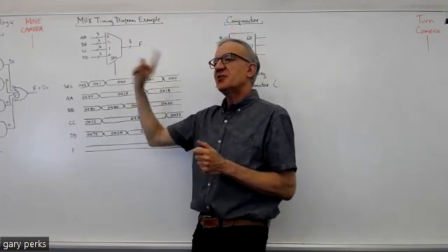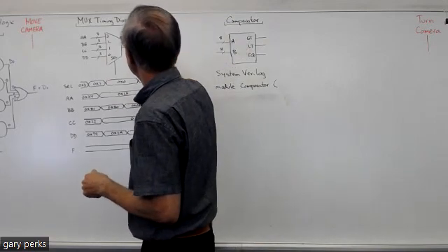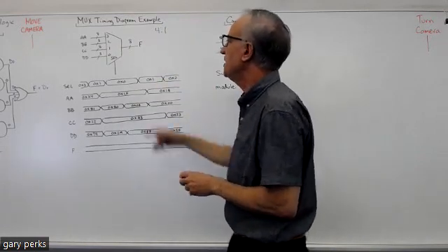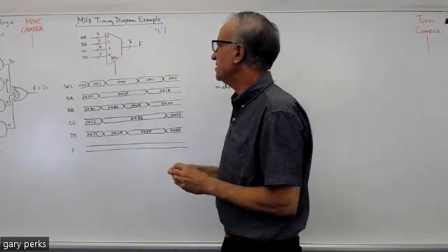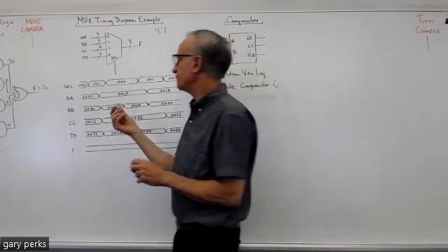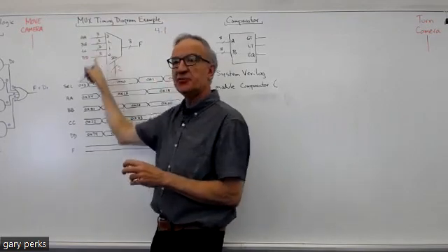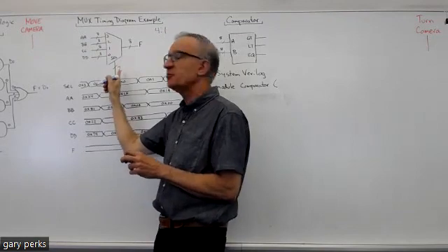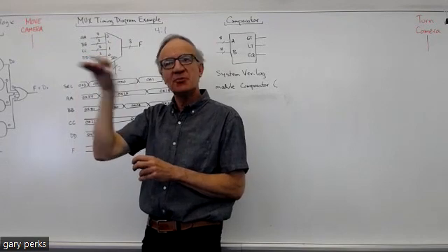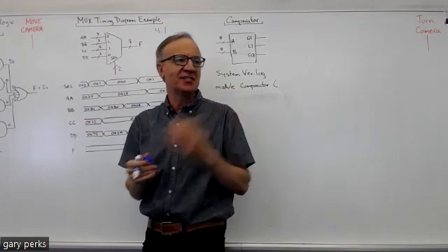So what kind of MUX is this? A 4 to 1. Yeah, 4 to 1. Again, this just means 4 inputs, 1 output. It's always 1 output, so the only thing that's different is the number of inputs. You can see we've got 4 inputs, and each of the inputs is 8 bits, and the output is 8 bits. How many bits would we need for the select since there's 4 inputs? 2. And again, it doesn't matter. If these were 16-bit inputs and 16-bit outputs, it would still be 2 select bits because the number of select bits depends on the number of inputs. The number of bits on each input has nothing to do with the number of bits for the select. That's the most common error people make.